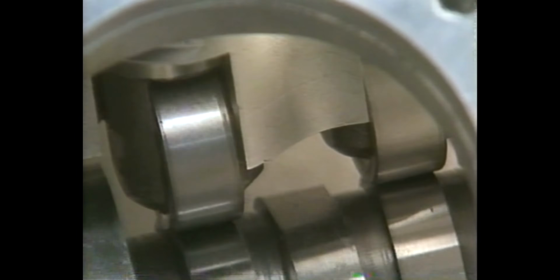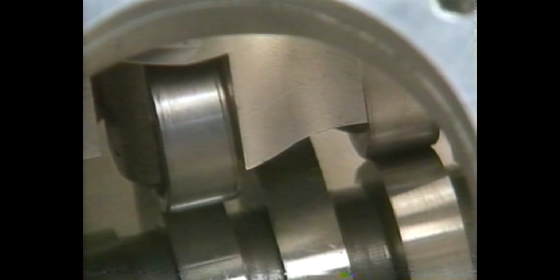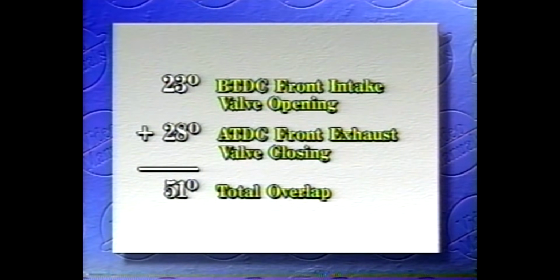Here we are using a Crane cam, part number 1-1003. The manufacturer's specifications for this Crane cam state that the intake valve starts to open at 23 degrees before top dead center, and the exhaust valve is closed at 28 degrees after top dead center. To calculate the overlap of this cam, we add together the intake valve opening at 23 degrees before top dead center and the exhaust valve closing at 28 degrees after top dead center, giving us an overlap of 51 degrees.